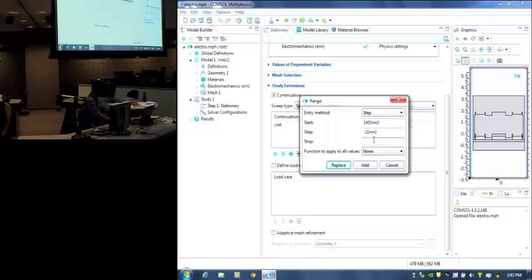Theoretically, we know that if it was a 1D lumped linear model, then at 1/3 of the gap, you would reach the potential required for making this resonator become unstable. So we're using that as a guess to sweep across the values, meaning you decide how many values you want to sweep across, and till what values you want to sweep across. So I've chosen the y-coordinates going from 140 nanometers to 120 nanometers, hoping that within this range it will collapse, or I'll get the pull-in voltage.